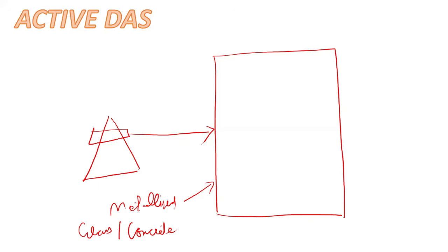So with an active DAS, you have a couple of ingredients. The first thing that you need is a base station or some form of signal source, right? So this is where you will have a base station. This base station may be connected to the core through the backhaul, but that is not our point of discussion at this moment. Okay. So from this base station, typically you will have a piece of equipment that we call a head end or the master unit. Okay. So this is the master unit. Any piece of equipment in the form of DAS head end equipment is typically located with the base station equipment. And then throughout the building on various floors, you will have remote pieces of equipment, right?